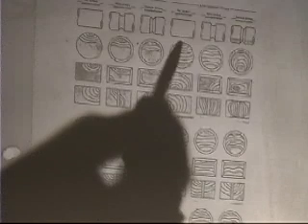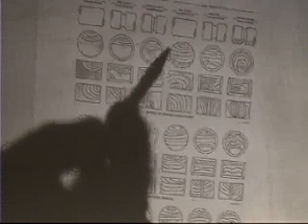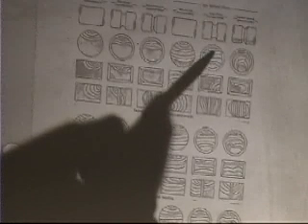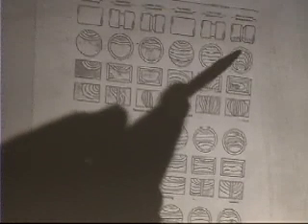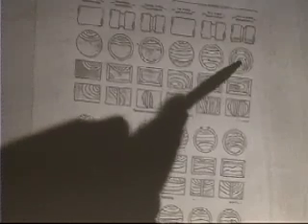So the point here is, if you're experienced at looking at fatigue fractures, you can just look at these things and say, well, the load on this was reverse bending, or it was torsion, or whatever. It's a high nominal stress or a low nominal stress. It had a stress concentration, or it didn't have a stress concentration, or in a case like this, there wasn't a stress concentration. And the difference between stress concentration and no stress concentration is that with no stress concentration you get, from the origin, kind of circular striations. With the stress concentration, they become more flat, and with a very high stress concentration, they essentially change their orientation.